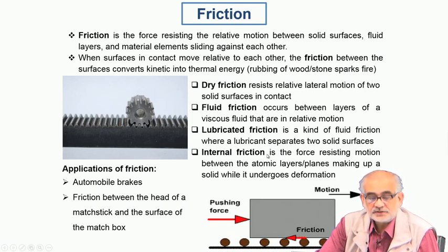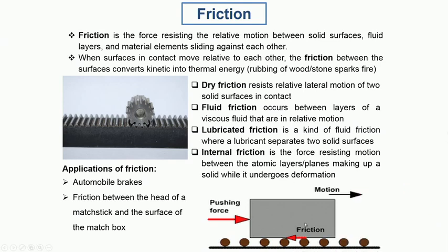We can also talk about internal friction. Now, this is something which is not visible by our naked eye. Essentially, it means that when we try to deform, the material tends to resist the deformation, and this resistance comes from the internal friction, which in true terms means the amount of shear stress a dislocation requires to be able to move on the slip plane.